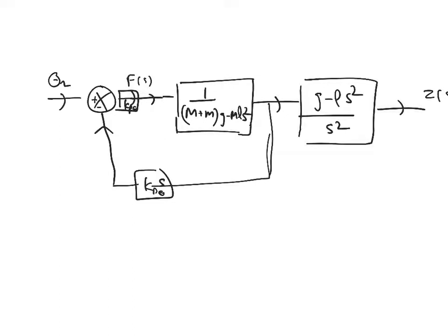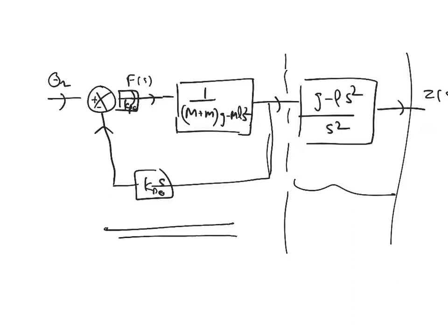So the objective is, whenever we design two separate loops, now we want to design a PID loop for this. So we need a bandwidth separation, how fast these loops are working. This loop works much faster than the outer loop, so the changes in theta will be much faster, so that we can have this loop separation.